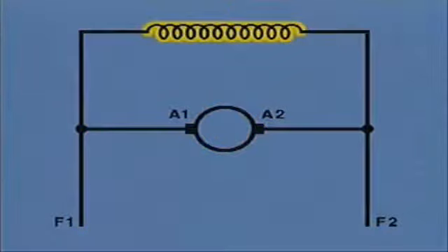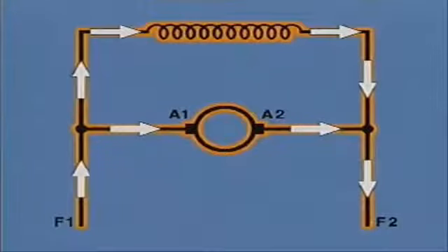Each coil in a shunt field is usually made of many turns of fine wire, so the resistance in the shunt field is very high. Because the resistance of the armature in a DC motor is very low, it's important to always install resistance in series with the armature before starting a shunt motor. If full-line voltage were applied to a shunt motor that did not have resistance installed in series with the armature, the resulting high current flow could severely damage the armature. Once the motor is up to its operating speed, the series resistance can be disconnected or bypassed.